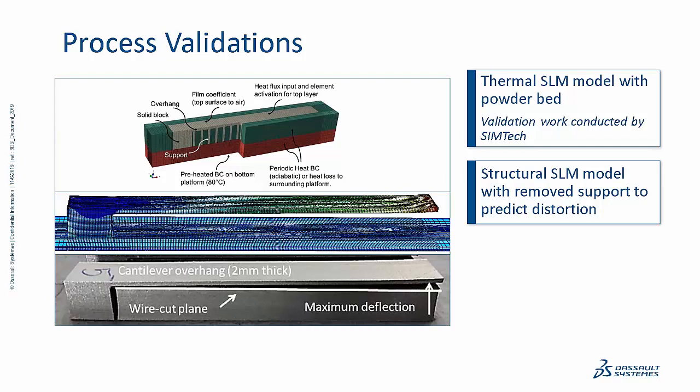Here is an SLM process validation, a joint work with SIMTech in Singapore. For the SLM process, overhanging structures with various support thicknesses was simulated. The influence of laser path, time incrementation, and surrounding powder bed material on the resulting stresses and distortions was evaluated here.